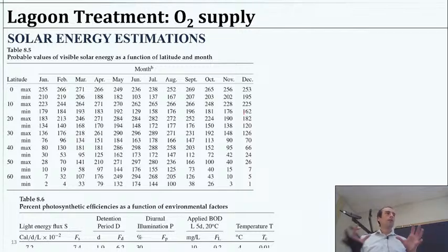So it feels very simply like, oh, we're just throwing all this wastewater in a pond and letting that be, but there is actually quite a bit of design that we can go into. Sludge accumulation in the pond would also affect that, because that's going to change the depth. So you would design, just like our septic tanks, for some number of years before you have to pump it out or dig it out, so that your process can still occur properly given your designed treatment flow.